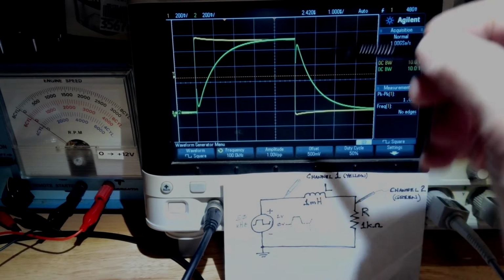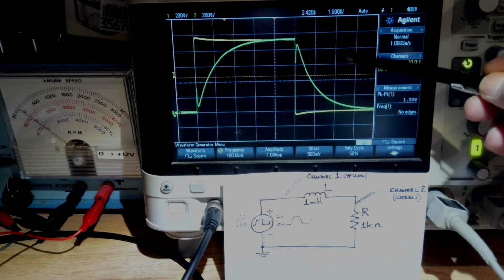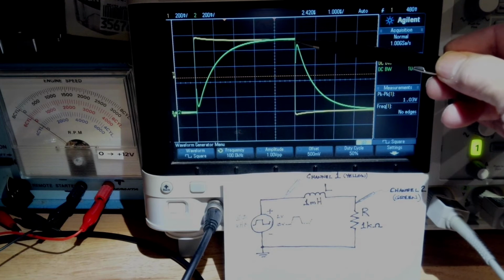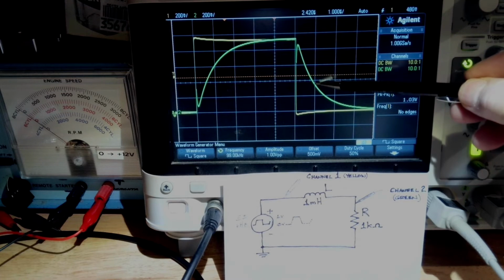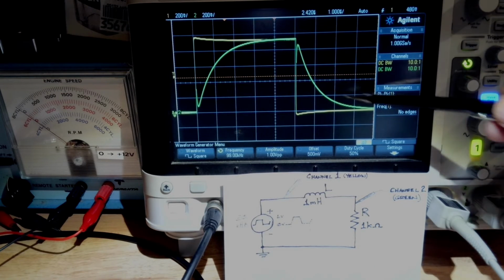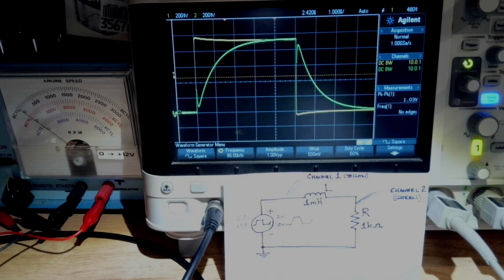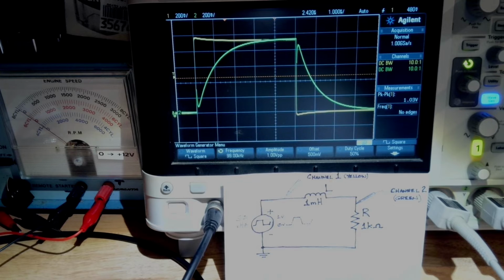And the same thing happens on discharge. If you come down from here, you drop down about 1, 2, 3 of these guys in one time constant. Okay? So there's the idea of time constant. Mathematically, it's L over R gives us the time. So once again, 1,000th of a Henry, 1 millihenry, divided by 1,000 ohms.